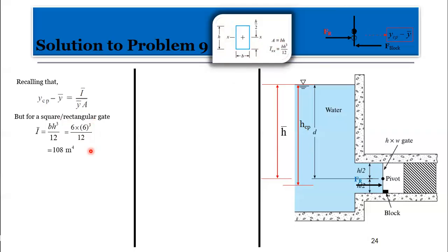Okay, good. So we need to now find Y bar. But remember here, we have everything in H. It is vertical, but we need a slanted what? Distance. Okay. And remember that sine alpha is what? Good. Sorry. H bar over Y bar. So since for a vertically immersed gate, alpha is 90, meaning what? H bar is what? Y bar, right? So sine 90 is 1, meaning H bar equals Y bar, right? So which is 12 meters.